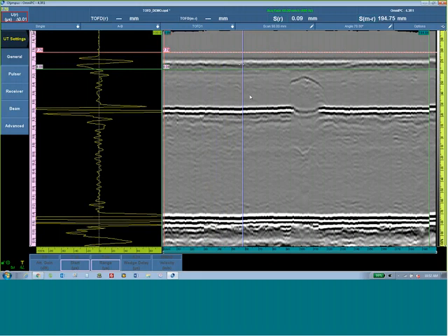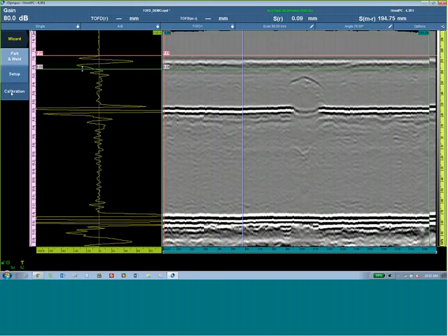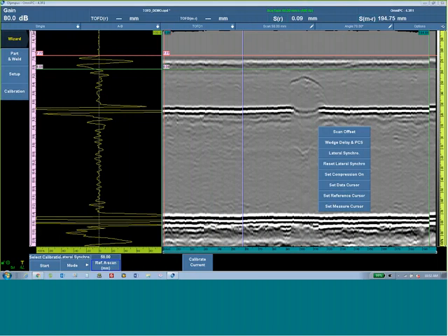When the lateral wave is straightened and I know that it is arriving at the same time as the calibration block, now I need only do a wedge delay calibration. The shortcut for the top calibration on the B scan will always display the last function used. We don't want to do wedge delay and PCS on the inspection data because we don't know the real thickness. It could vary 10%, or it could be corroded or anything.